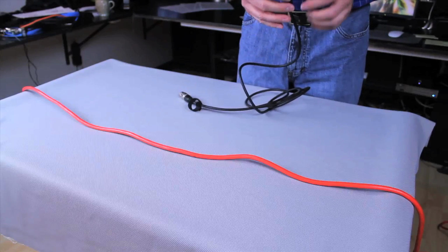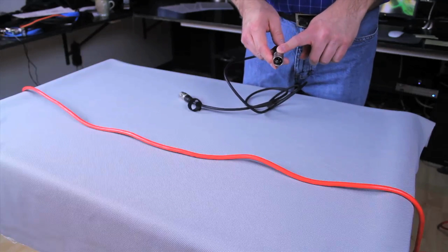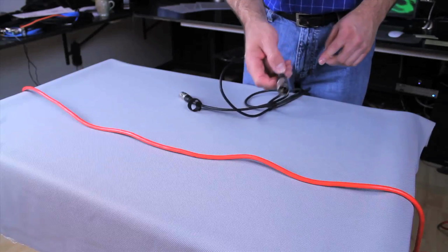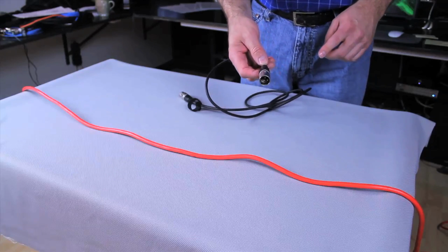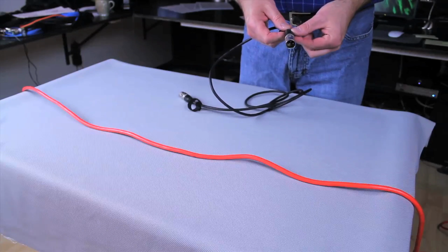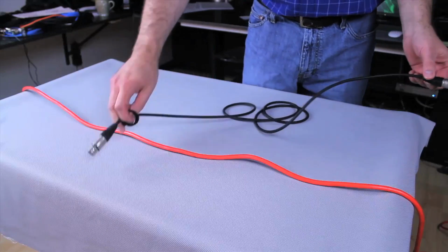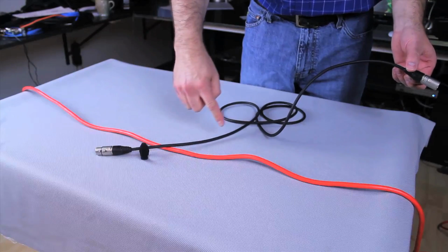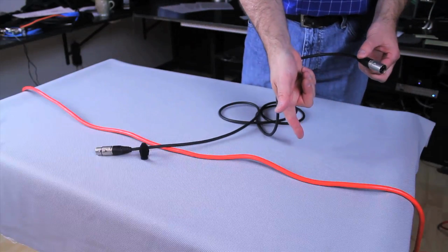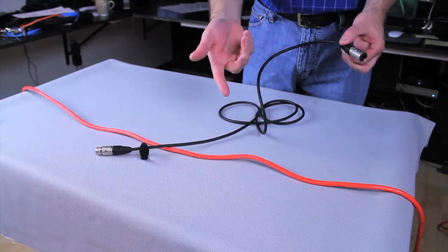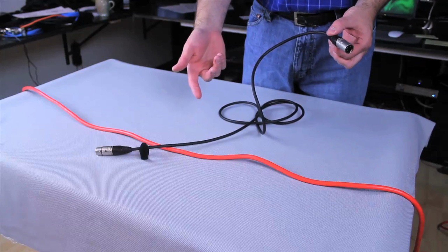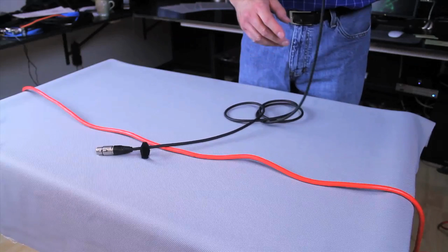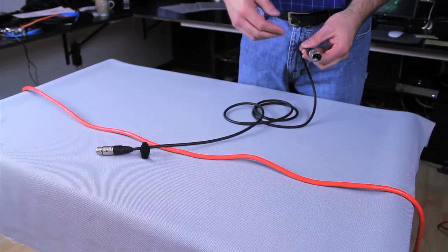I do it on the end that I'm going to plug into the audio equipment, the last possible moment where the mic is going to plug in, and the ground is cut. So that way, if it's picking up any kind of RF, in my mind I think that it's going down and it drains off into nowhere. And I've had that actually explained to me by an electrical engineer. Yeah, it's called a drain. And that's ways around those kind of problems.